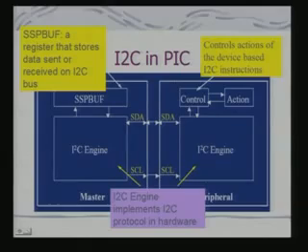In fact, in a more general case, if you remember, I said that the I2C bus has been used as a control bus for connecting various peripheral devices. So if the peripheral device has a set of commands, then those commands will be transmitted via the I2C bus. They will be detected by the I2C engine and passed on to the control logic, so that there can be device specific action. Okay.